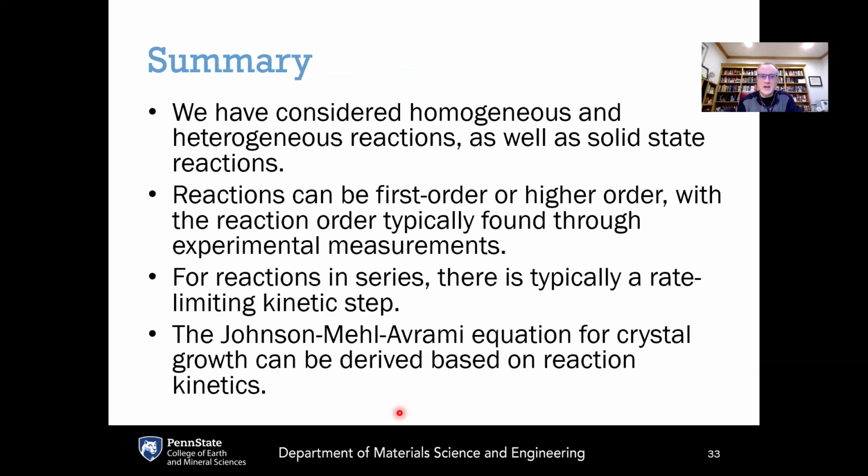So to summarize, we have considered homogeneous and heterogeneous reactions, as well as solid-state reactions. Reactions can be first order or higher order, where the reaction rate is typically found through experimental measurements. For reactions in series, there's typically a rate limiting step. And we've shown how you can derive the Johnson-Mehl-Avrami equation for growth based on reaction kinetics.